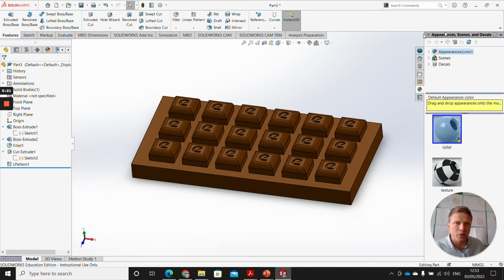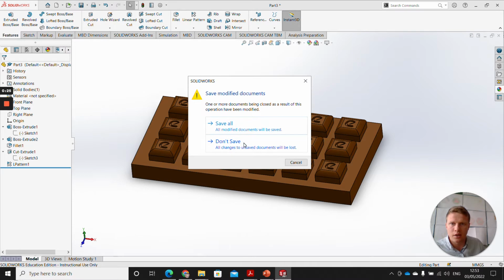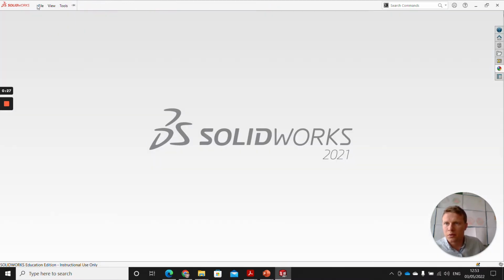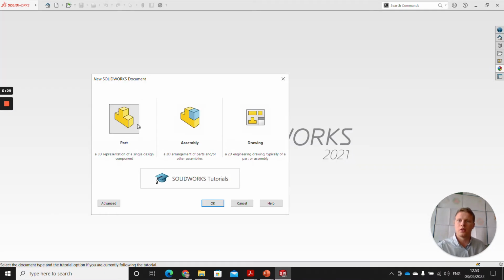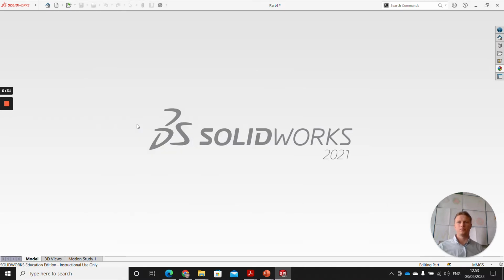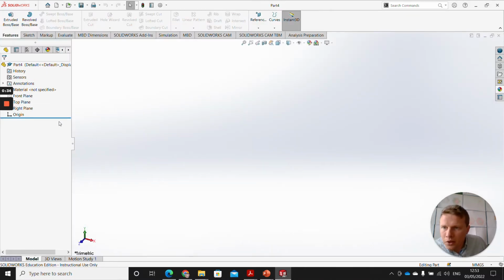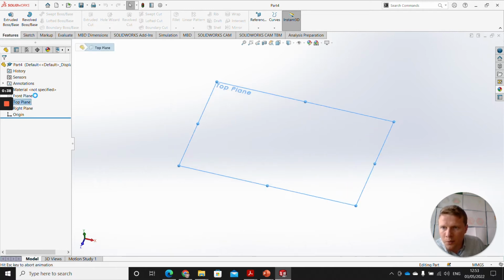So first of all, we're going to set up a new part. This is the one I've drawn earlier. I'll exit out of it. So File, New, and double click part. So what we're going to do first of all is click on our top plane like so, and then click sketch.